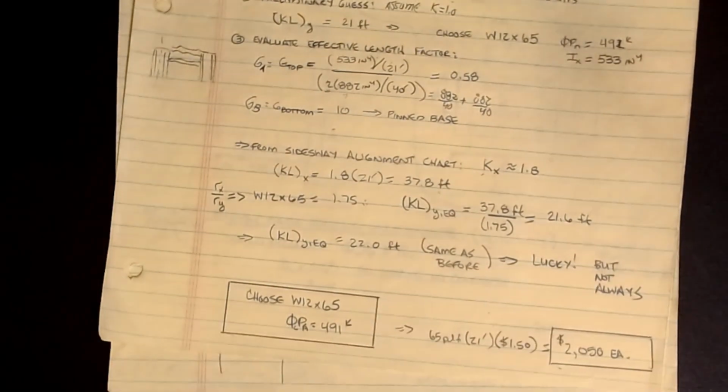Okay, now there are other methods that you can use to do this. We're just doing kind of a direct stiffness method kind of thing. We're assuming everything is in the elastic range. If for some reason you choose a column that gets out into inelastic behavior, and you're looking at something like secondary effects, what we call P delta effects, then you have to do something a little bit different, but we'll save that for a discussion for another day. Here we're assuming we're staying well within the elastic range as we design our structure, and we're not worried about getting out into any of those other ranges where stiffness reduction becomes an issue.